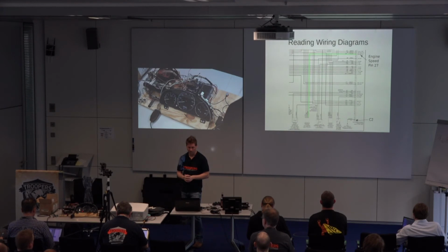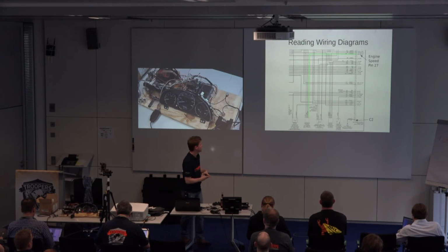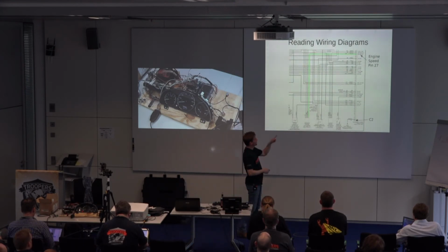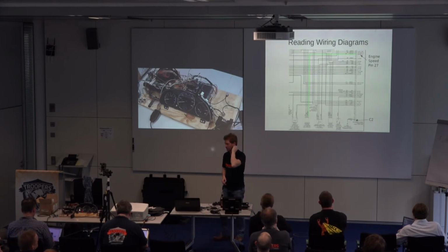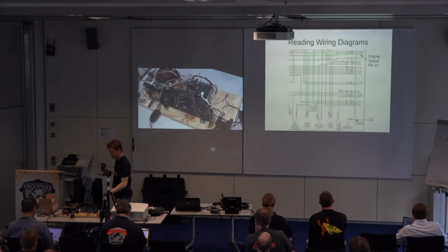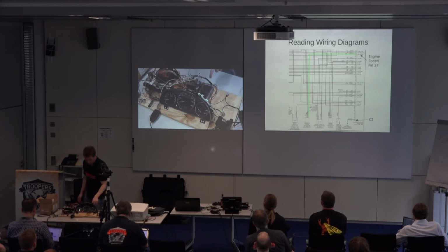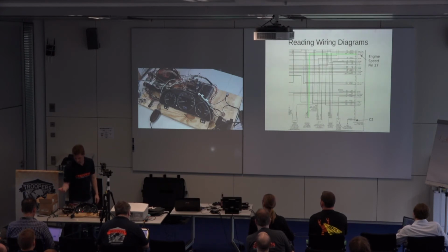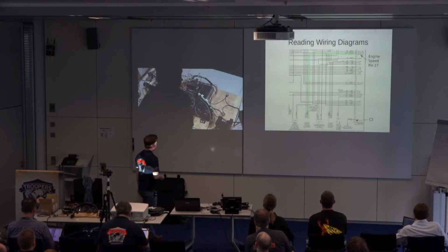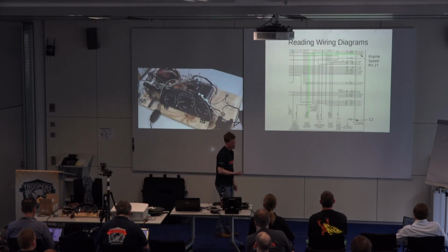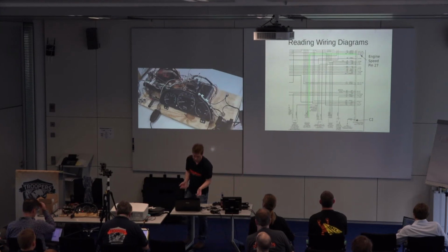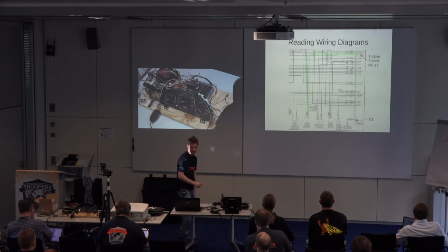And so, like, okay, if I want to figure out like the crankshaft position sensor, first what I do is I figure out which wire it is. And in this case, I see that it's pin 27 on C2. It's really hard to read those. I try to make it as visible as possible. That connects to the crankshaft. And then you can basically find out that it's kind of labeled C1, C2, and C3. C2 is in the middle. And then you have to literally like find pin 27. And that's the one you're going to break out. And if you're unfamiliar with some of these, you just really would then go to Wikipedia or somewhere to look up how crankshafts work. And you can, why does it do that?